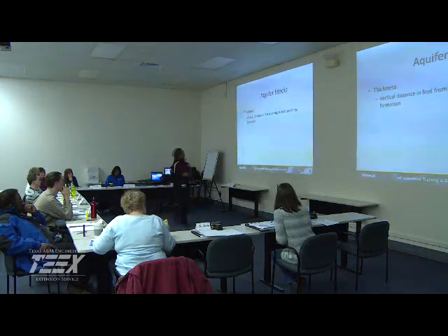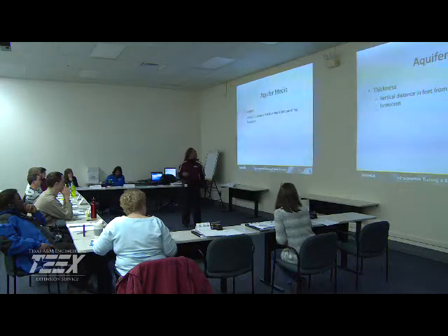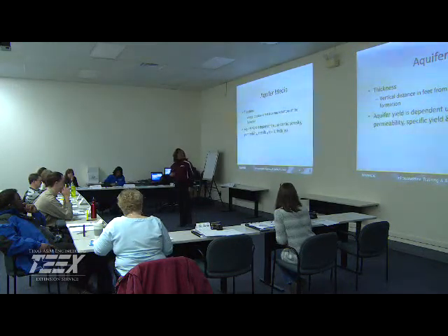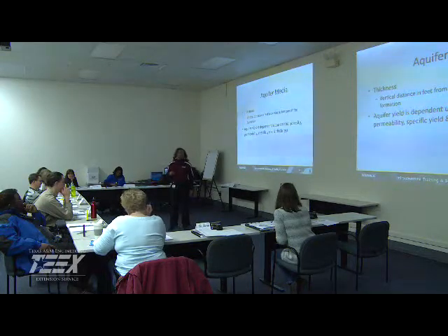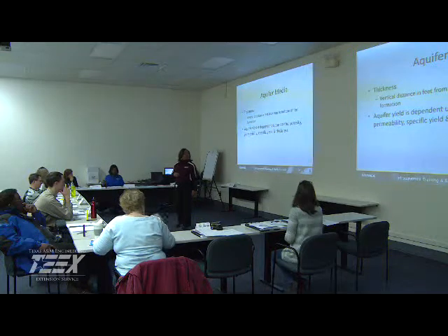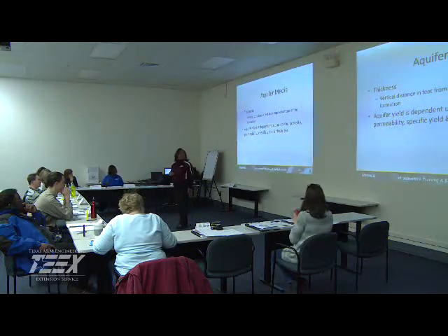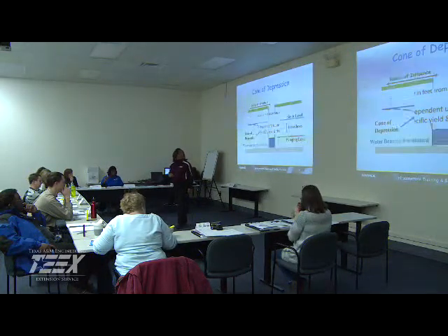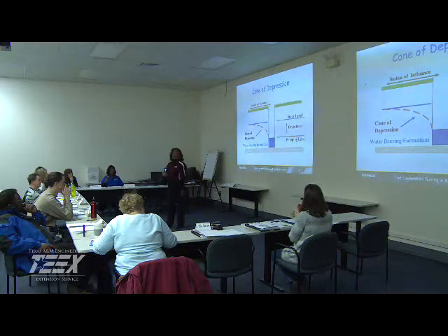All right, the thickness is simply the vertical distance in feet from the top to the bottom of the formation, and the aquifer yield, how much you're going to get from that aquifer, is dependent on porosity, permeability, as well as the thickness. That was one of y'all's test questions for your state?